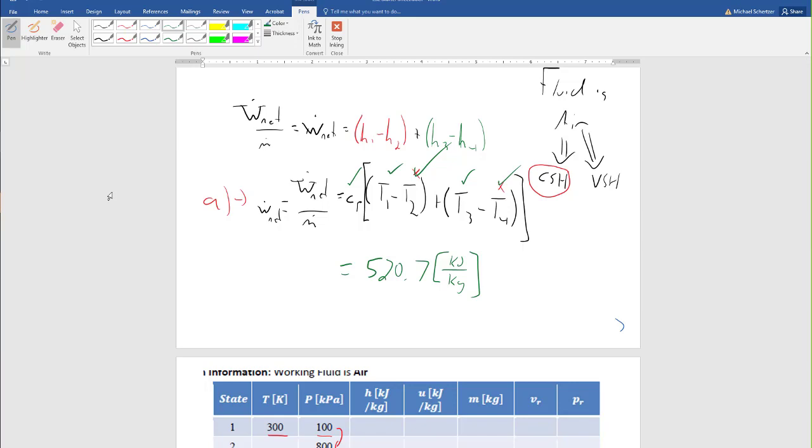A wrinkle you could get, so you could get isentropic efficiencies on the turbines or the compressor, right? Or it could be variable specific heat, in which case the flow chart looks the same, but when you do those isentropic processes, you have to use not an expression with K in the exponent, but something that's P over P is equal to PR over PR. So you have to use the variable specific heat version. And then there'll be some interpolation on table A22, right? You'll find the temperature at state 1, which will let you find PR at state 1. And then you'll use the ratio of PRs because it's an isentropic process to get to state 2. That'll give you PR2. You use that to find H2 and then T2. And then you do that same process back and forth in the turbine as well.